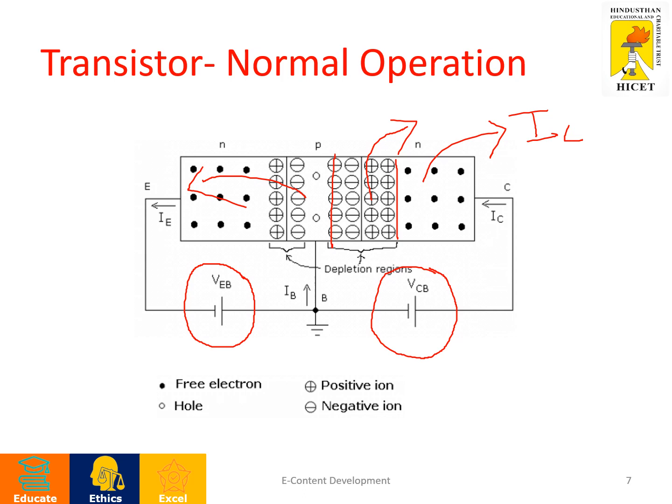Just like a PN junction, once it is forward biased, this depletion layer easily breaks down and there will be a flow of current, whereas here the width increases, so there will be minimum current flow based on the minority carriers at this particular point.